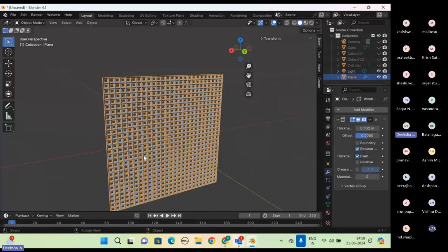Let's say I add a mirror modifier to mirror a body, but after some time, I've completely drawn the symmetrical part and now I don't want the other parts to be mirrored. In a case like that, there's an option called apply. Once you apply, the body will stop mirroring, or the use of the modifier comes to an end there itself.